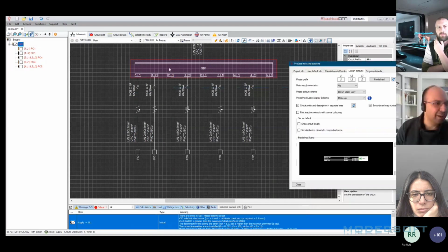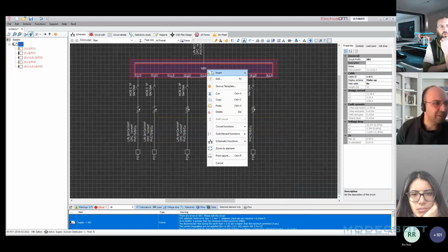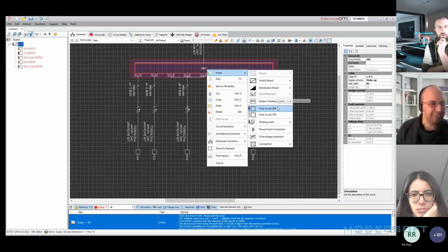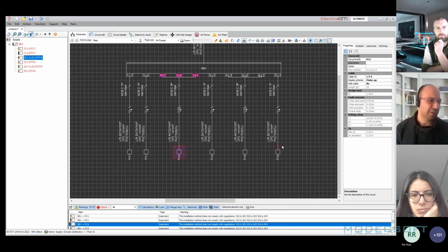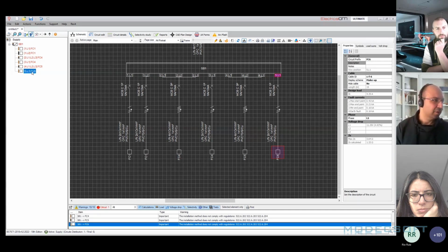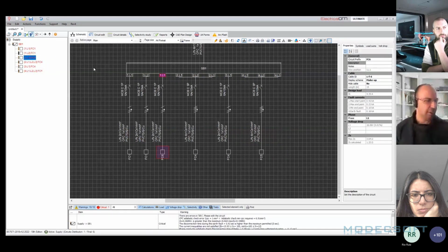So now if you put in another three single phase ways off that, you'll see how the numbering will just keep adding as you go along. Okay, I'll try to move this to here between these single phase, the FC1, and this 3-phase circuit, which is FC4, and see how it will be numbered if I manage to move that up there. Okay. Now you see that it is